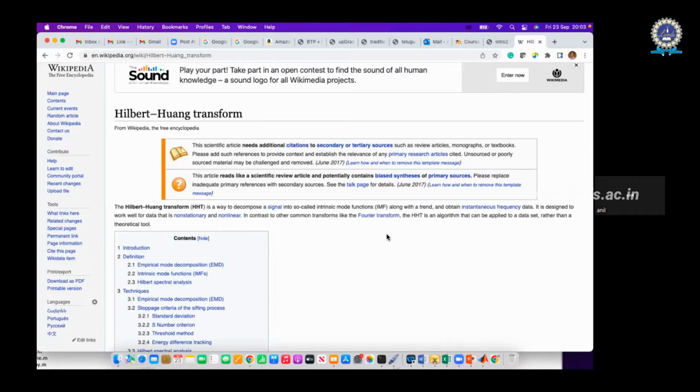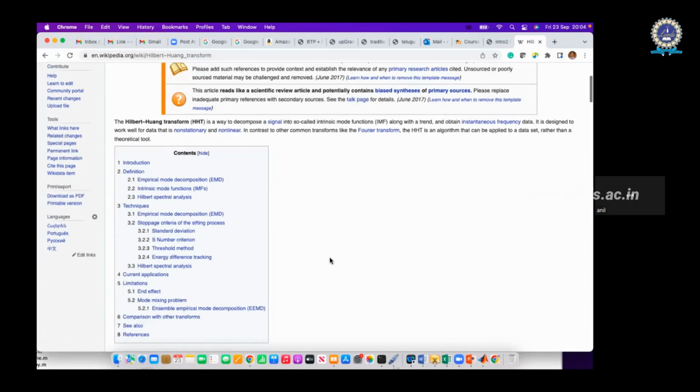So if you want to get any information or prediction from that, we need to be careful. We can't apply short-term Fourier transform or wavelets etc. on the data, because that is information we are getting from the effect of multiple sources. So what they do in this Hilbert-Huang transform is something called empirical mode decomposition.